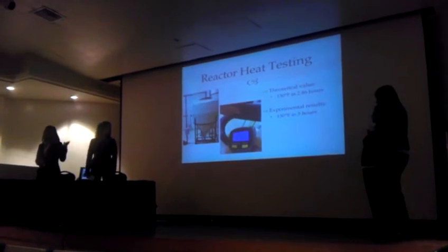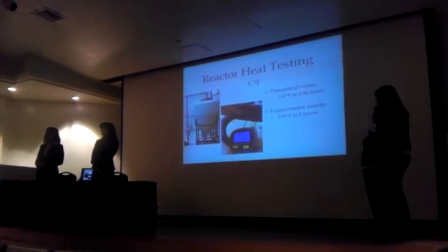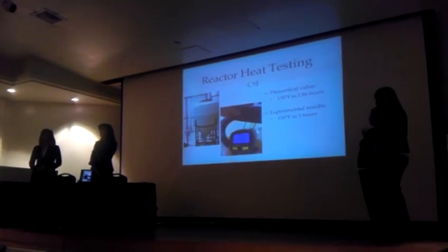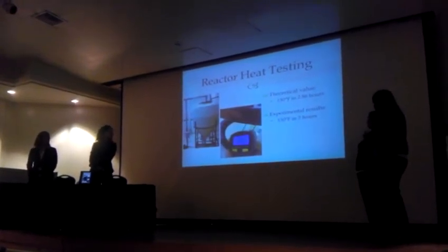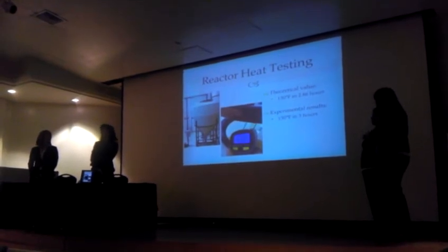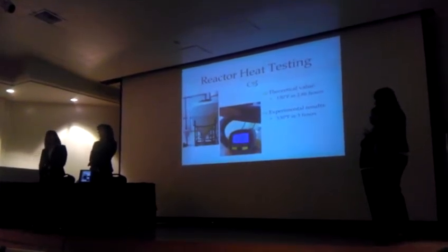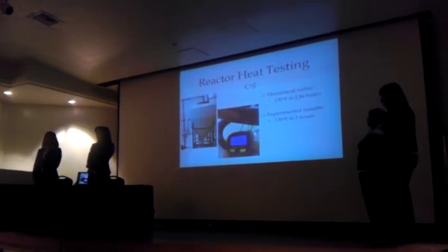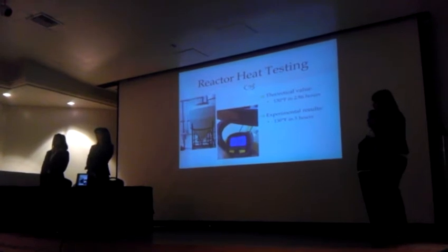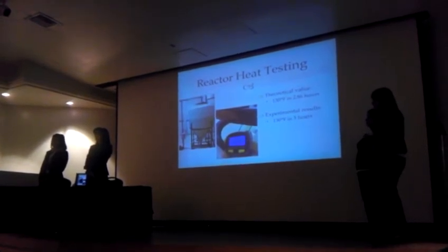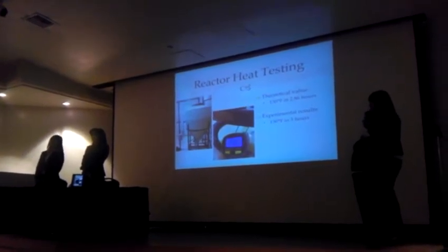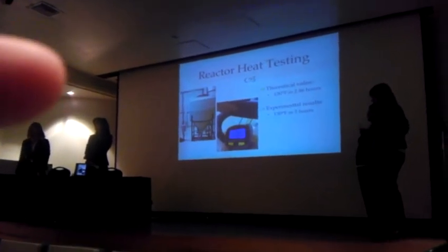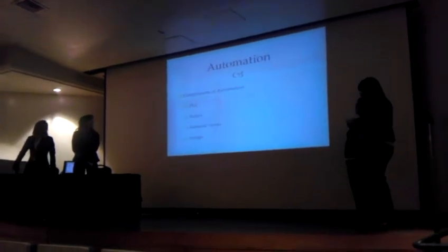We used the same equations from earlier for the filtering heating process, and the theoretical value that we came up with to heat water at 130 degrees Fahrenheit takes about 2.86 hours, and our experimental value after timing it was about 3 hours. And we figured that this was very reasonable since there was some heat loss in the system, the lid wasn't on all the way, and we didn't put in any of the insulation since we're going to have to take it apart anyway to put it outside. So it seems really reasonable.